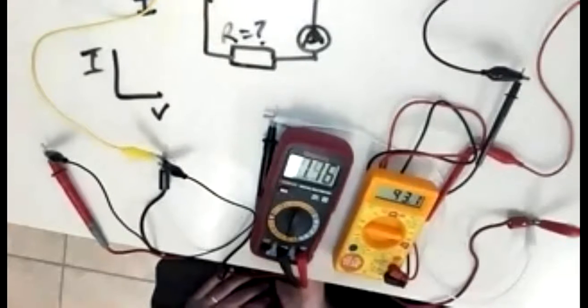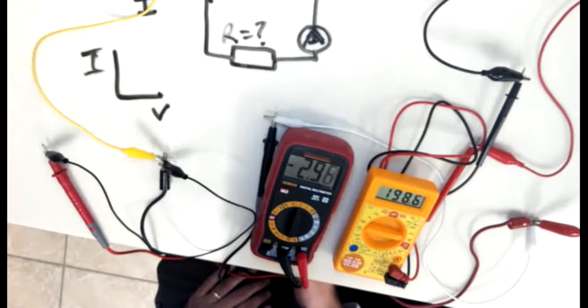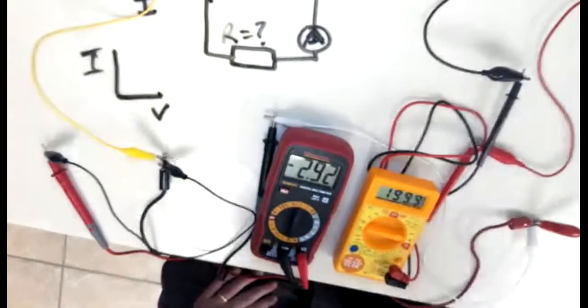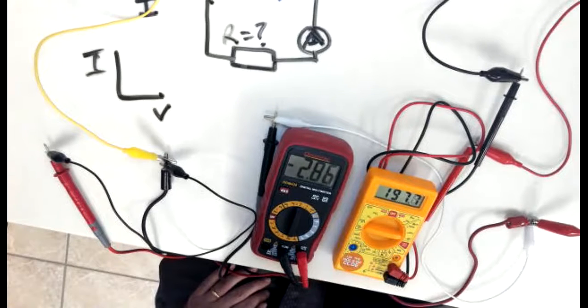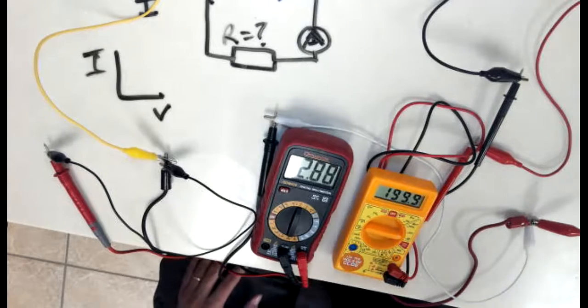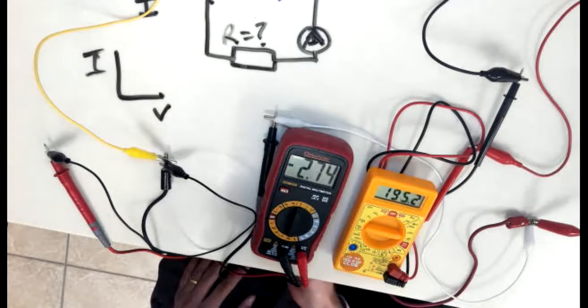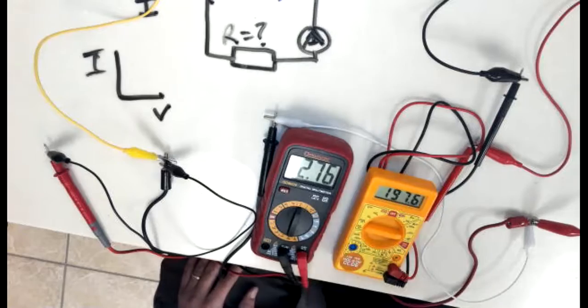About 1. Let's try to crank this guy up. When the voltage is 3, see, I'm really right at the edge of that 200 milliamp range. You see how it's almost overloaded? And that 1 means it is overloaded. So let me just back it down. 2.85 volts, 198.9, 199.1. Pick a number there. See, it's almost overloaded. 2.75, 196.0.